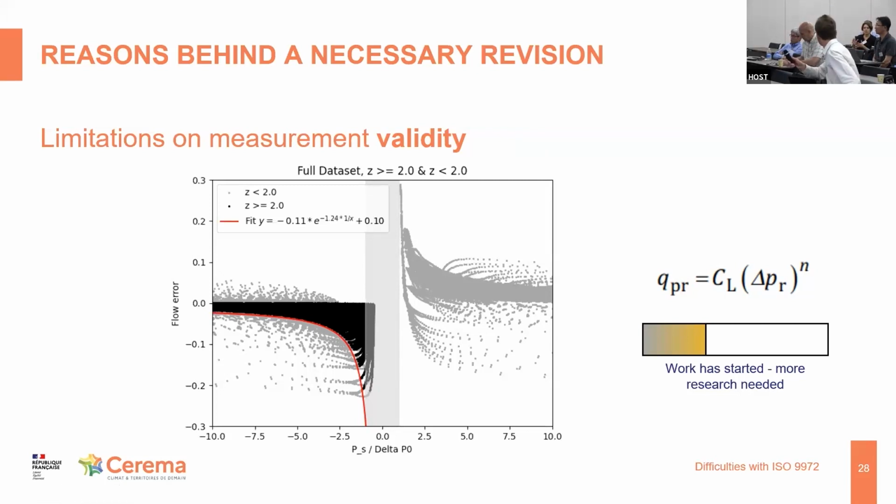Yeah, this is the ratio between the measurement point and the zero flow pressure. Whatever the zero flow pressure is due to, it can be due to wind, it can be due to stack effects. The most important thing is that there is a zero flow pressure that is big.